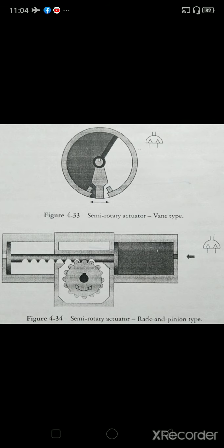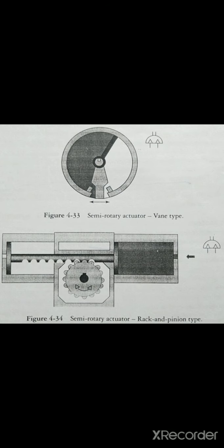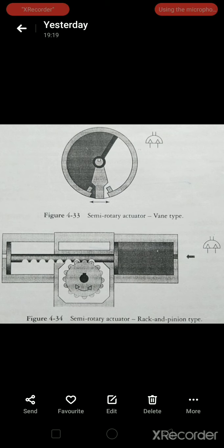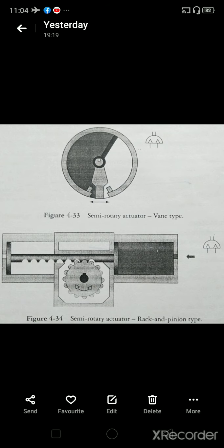Rotary actuators are employed for continuous movement of scrapers or knives in the paper making industry, or as a flameproof drive for mixers and stirrers in the process industry. They are used for moving conveyor belts or as a power drive for reciprocating machine tools. Other applications include the operation of liquid pumps and the movement of an oscillating coolant nozzle in cutting operations.